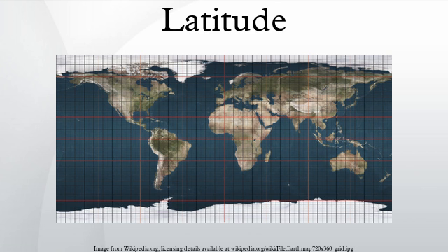Its most important application is in the theory of ellipsoid geodesics. Rectifying latitude. The rectifying latitude, μ, is the meridian distance scaled so that its value at the poles is equal to 90 degrees or π/2 radians. Where the meridian distance from the equator to a latitude φ is given, and the length of the meridian quadrant from the equator to the pole is given.